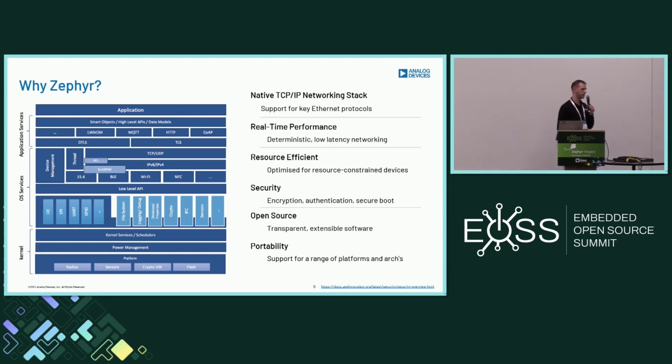So Zephyr obviously is an RTOS, and while it's not always a hard requirement to have real-time capabilities on embedded systems like this, implementing low latency networking is often a requirement for industrial applications. So Zephyr provides those capabilities. Resource efficiency is also a factor in lots of embedded systems, but again, when you're considering pushing connectivity to the edge where you have a simple MCU, ARM Cortex M0, M4 with limited RAM and flash, resource efficiency is critical. So Zephyr is highly optimized for these types of applications.